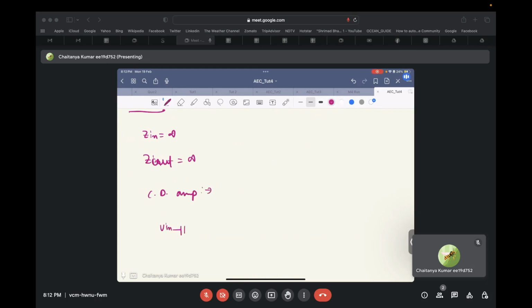We have V in at the gate of the circuit. It's not basically a common drain amplifier. It's like a version of common drain amplifier. So there is some load resistance to which we need to supply current, a voltage controlled current source with some kV in. It was discussed in detail how the circuit comes about.